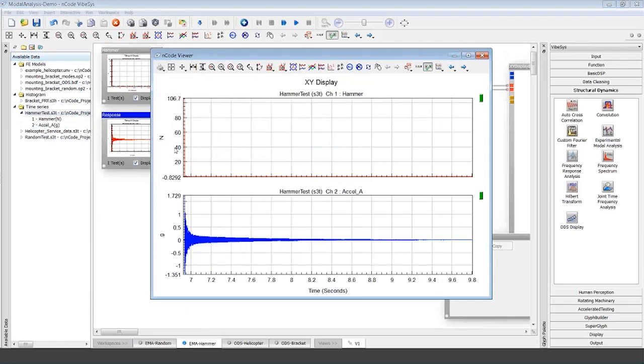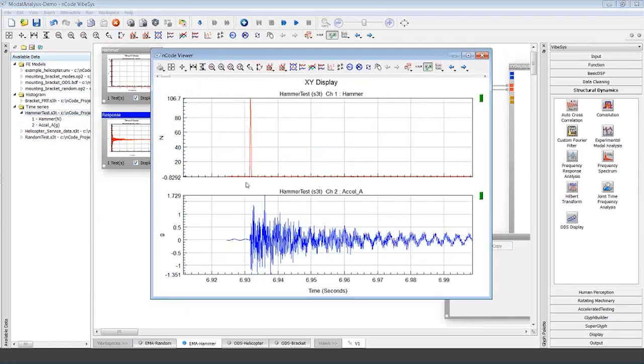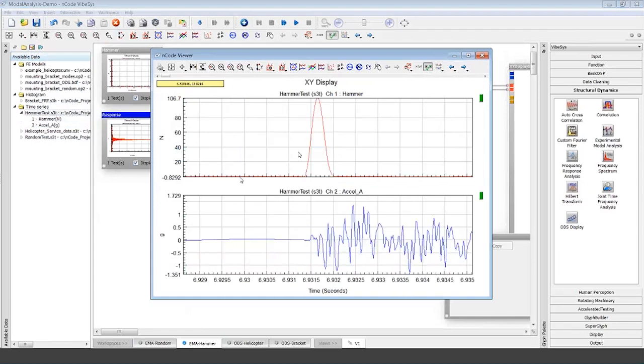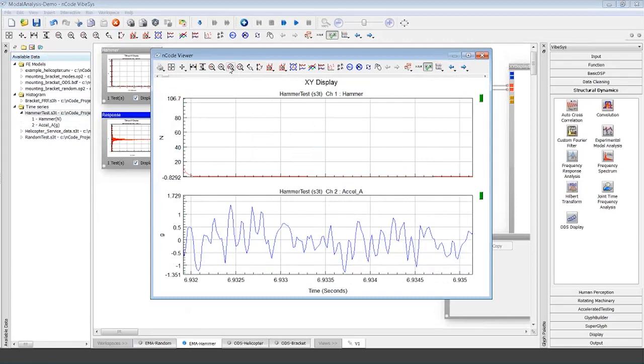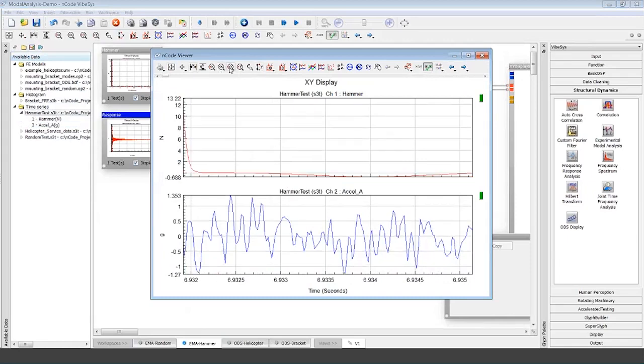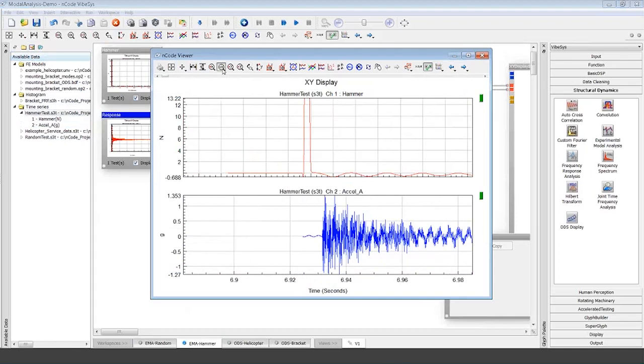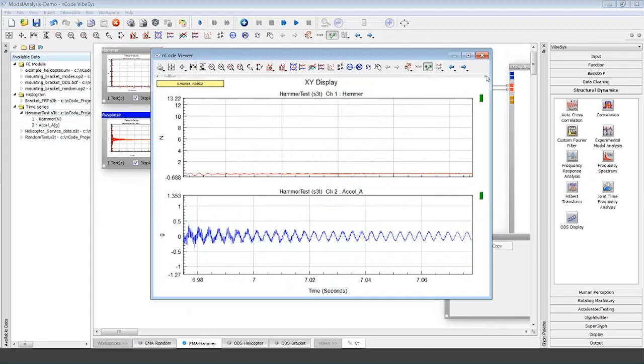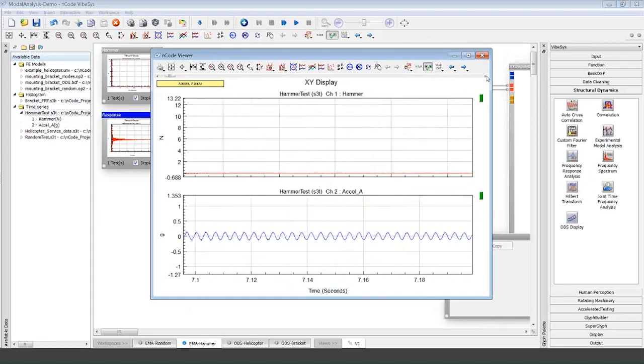We've got the hammer excitation signal. Basically, it's an impulse here. We've given the structure an impulse, and then it decays quite rapidly. And below you've got the response in terms of acceleration at a specific location, and it also decays. Oh, it takes its time to decay. So there must be very, very low damping for apparently one mode, because it looks like a sine wave.